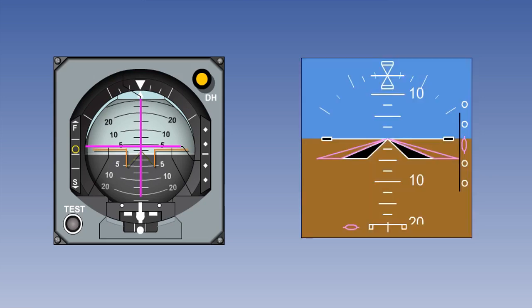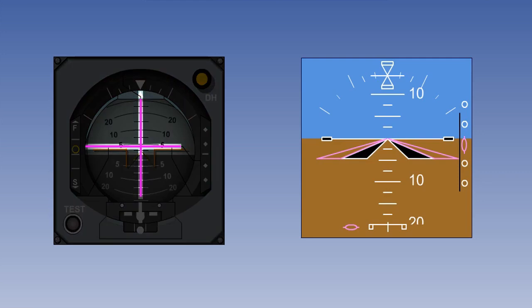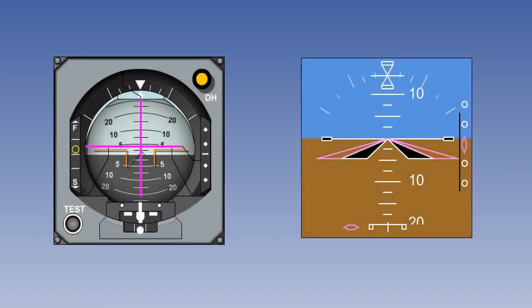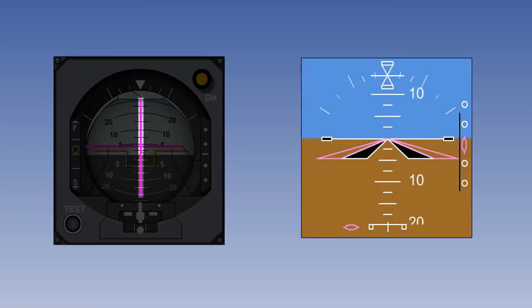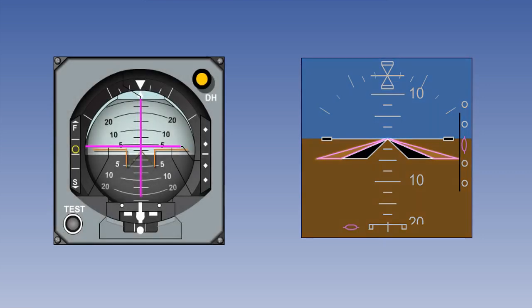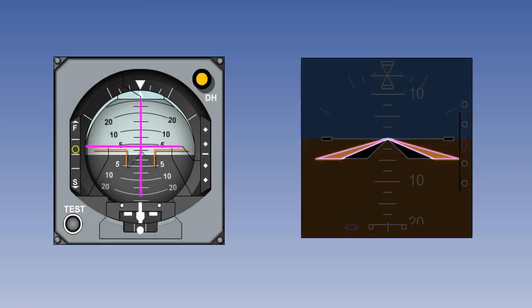The flight director system uses one of two ways to display the information, either using twin bars forming crosshairs or a V-bar. Both demand pitch and/or roll inputs from either the pilot or the autopilot. With the twin bars, the vertical pointer displays roll commands, and the horizontal one displays pitch commands. The V-pointer moves as a whole unit to command roll and/or pitch inputs.